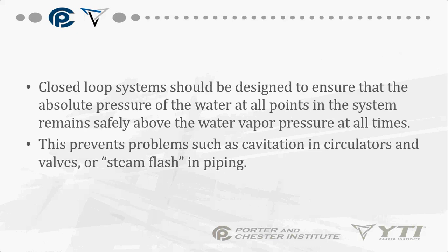Another way for it to rupture is if I just simply add too much water to the boiler, which is why a boiler has a water feed valve. Water feed valves operate based off of the boiler pressure. If the pressure drops in the boiler, that water valve will open to allow more water in. And when I'm allowing more water into the system, I raise the pressure again. If I overfeed it or fill it up too much, I'm going to raise the pressure too much. I'm going to rupture my relief valve.